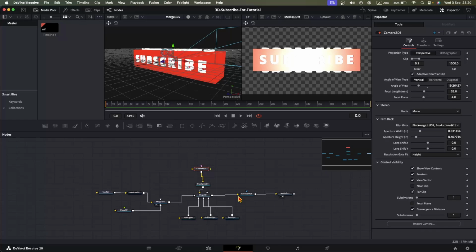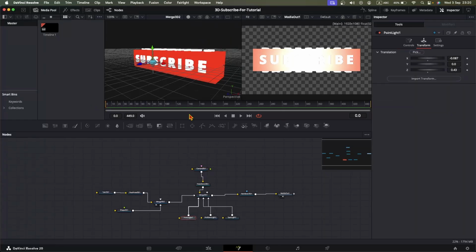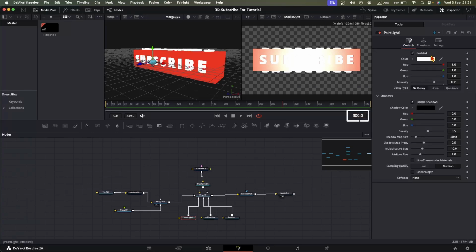First of all, we will animate the lights. Select the point light and go to frame 0. In the frame 0, intensity is as it is, but then go to frame 300. You can type it here. And in the controls, in the intensity, click on this diamond icon here to add a keyframe and change this to 0.386.